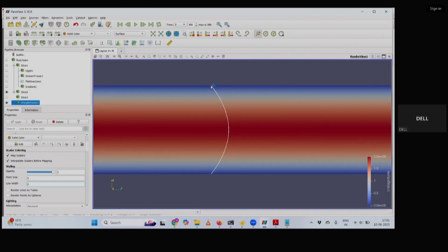What other kind of data can we calculate from here, just like the velocity profile and the pressure profile? Earlier I was showing the vorticity also, right? As this is a steady state, you will not get much variation in the vorticity, but still you can calculate it. Or if I want the wall shear stress, then how can I extract this animation?